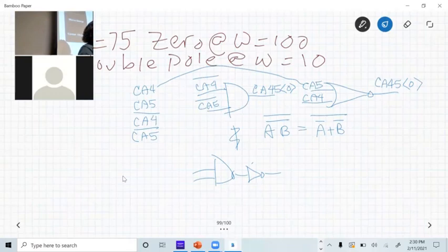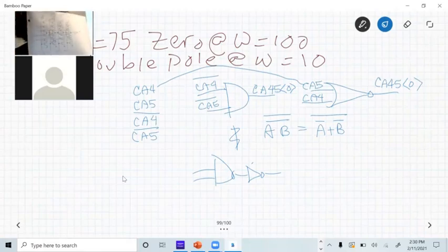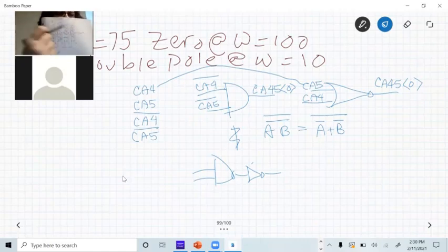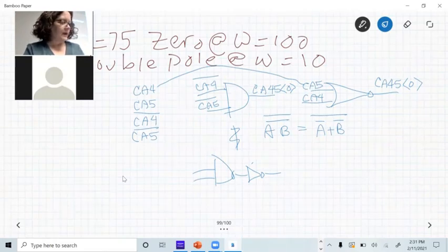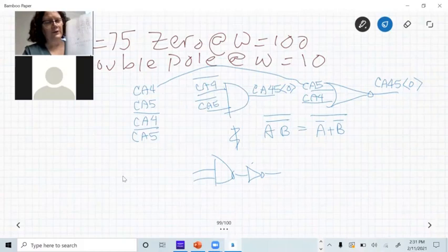So it references the diagram in the book. And you go and you find the CAM part of the circuit, which is this string of transistors. It's in the upper left-hand corner. There's a whole bunch of spaghetti in here. In order to decipher the spaghetti, I literally wrote on the gate of each one of those transistors what signal was going there. All those signals would have to be true going in, and then you figure out the logic function.